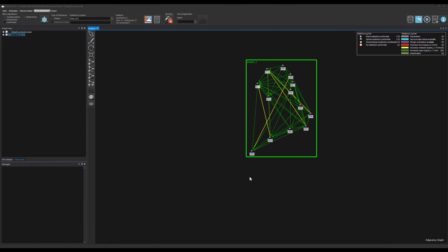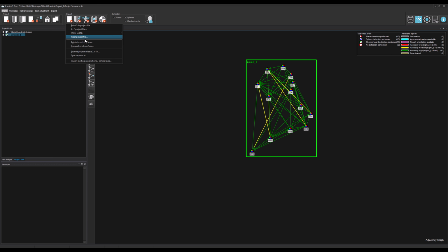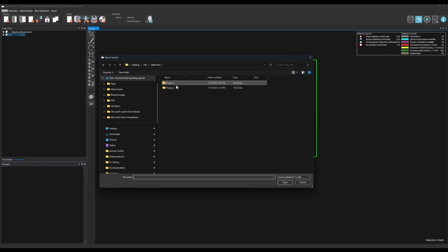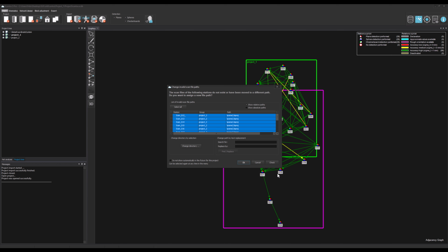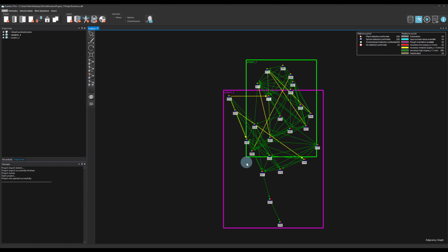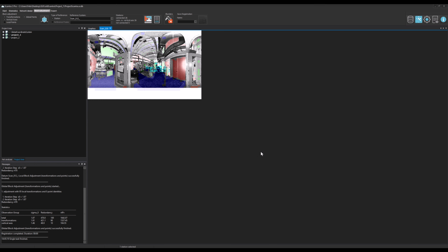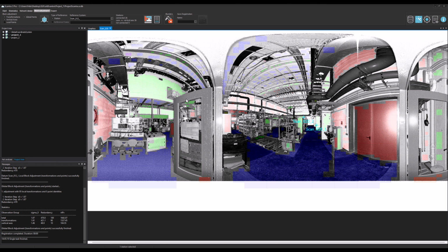This functionality is designed for users who want to import already completed projects or projects that are composed by individual parts into a new Scantra project. This can be achieved by navigating to the entry Scantra projects from versions 2 and 3 under Import Data. Using this function imports all entries from one database to the other. Given the case that identical group names are being used in different projects that contain different scans, all scans are imported into one group. Bitmaps from projects that are potentially stored at different locations are being copied into the directory of the current project.